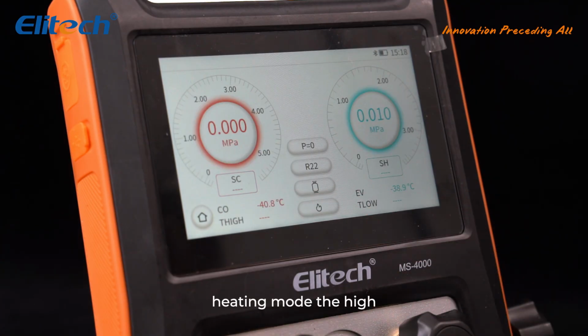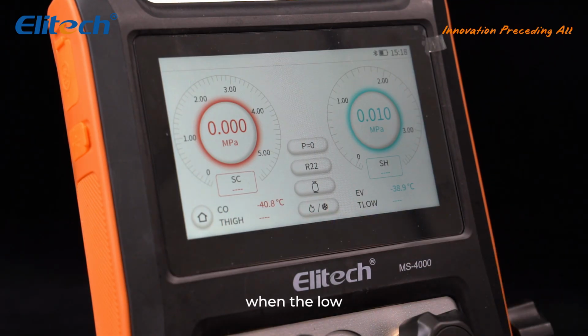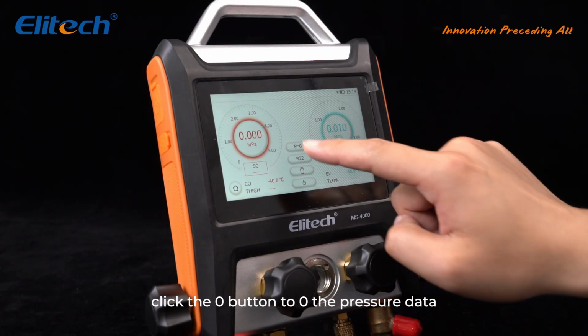Heating mode: the high pressure and low pressure parameters will be switched for display. Heat pump mode: when the low pressure side pressure is 1 bar higher than the high pressure side pressure, the corresponding parameter display positions of the high and low pressures will be automatically switched. Click the 0 button to zero the pressure data.